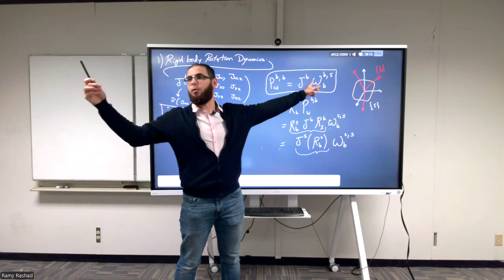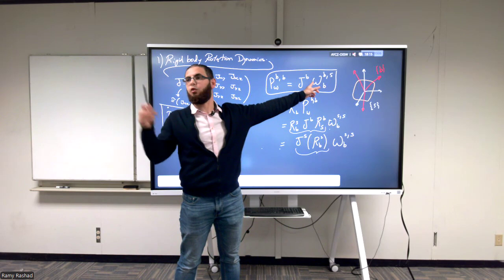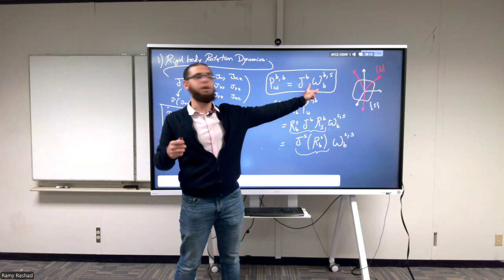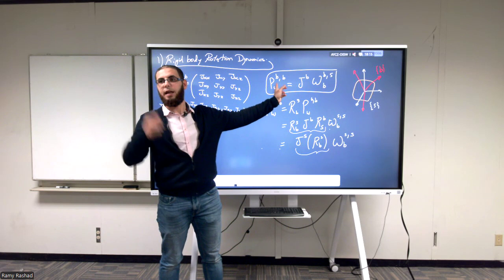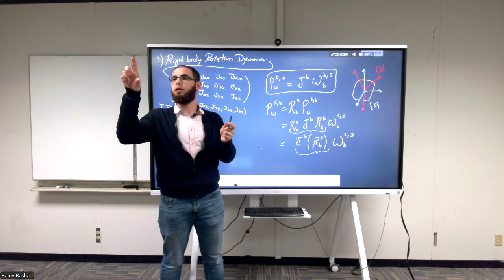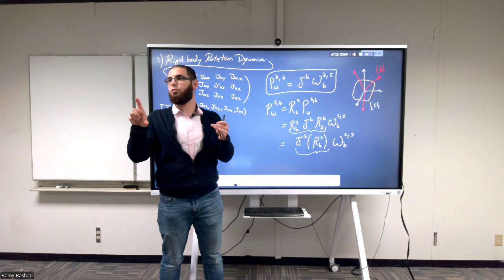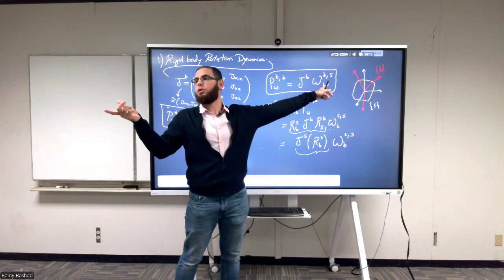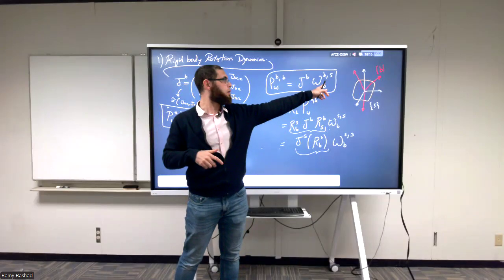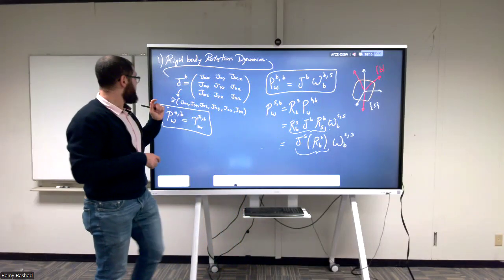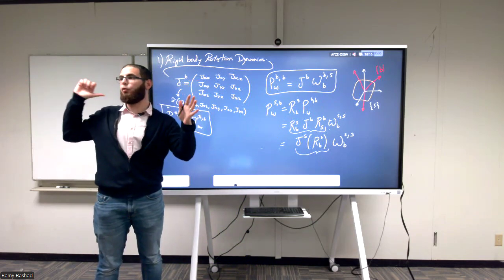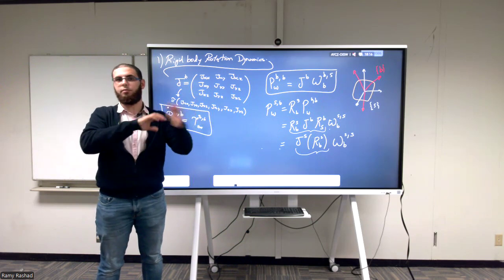So the inertia tensor, first of all: what is the equivalent to the angular velocity when we talk about rigid body motion? A twist. What's the dimension of it? 6 by 1. What would be the corresponding inertia that's multiplied by it? A 6 by 6 matrix. What would be the momentum? A 6 by 1. The first three would correspond to angular momentum, the second three to linear momentum, same as with the twist. The first three corresponded to angular velocity, the second three to linear velocity. The inertia tensor will be a 6 by 6 matrix. When we look at it from the body frame, it will be fixed. When we look at it from another frame, it will not be fixed.